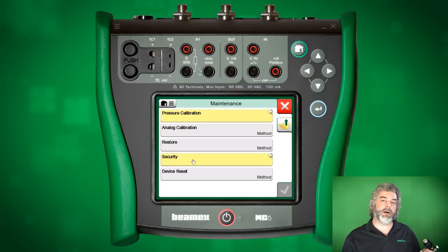This varies depending on what manufacturer you're looking at. Sometimes even different models within manufacturers, it's different. But if you mess up and go to the wrong place, just do the up folder to take you to the upper level. If I hit the X by accident, it'll dump me out of the communicator and I'll have to go back in again.